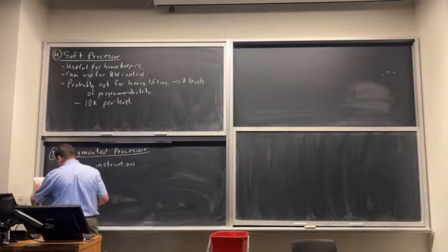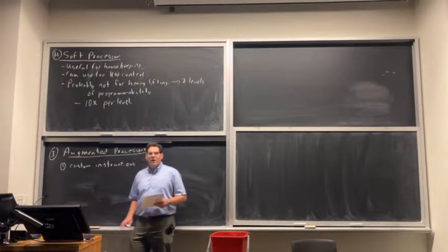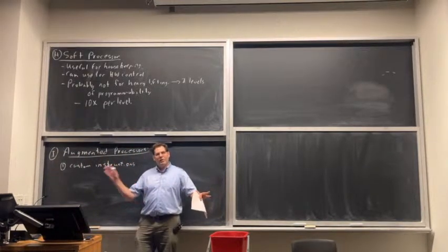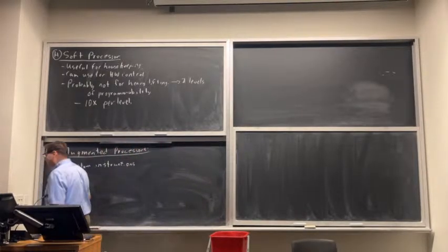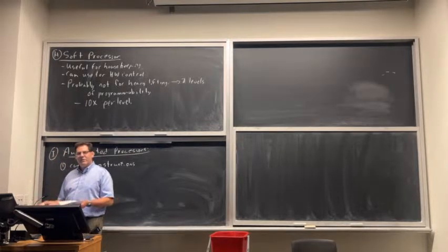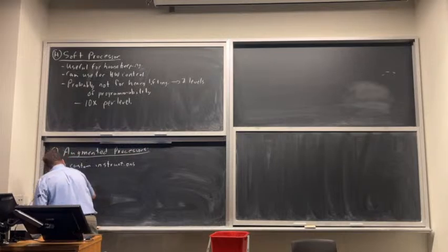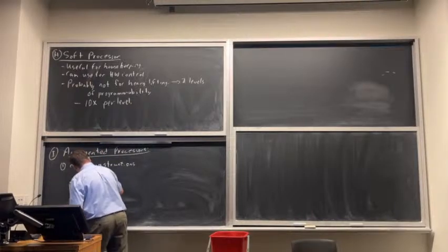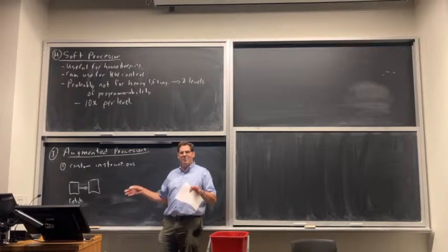Most of these soft processors, there are really cheap ones, there are somewhat more expensive ones, and ones in the middle, and when I say expensive, I mean how much logic they take. The one I'm about to show you would take maybe 1,000 or 1,500 logic elements. They use a classic 5-stage pipeline. Who knows what I mean by a 5-stage pipeline? You all remember that from computer architecture?